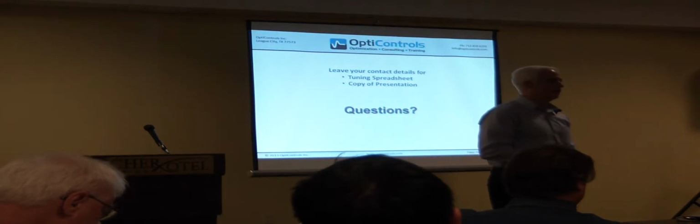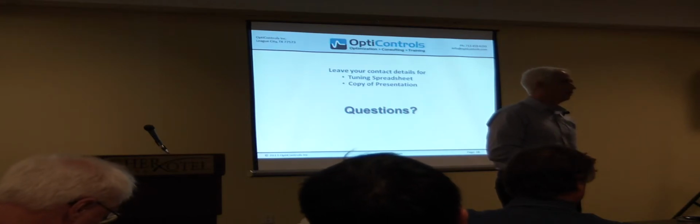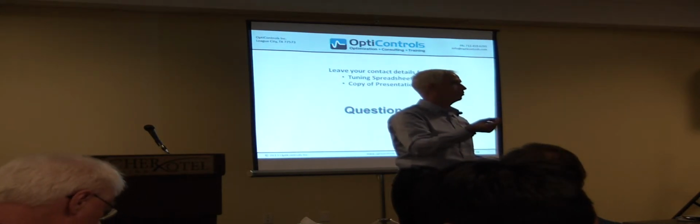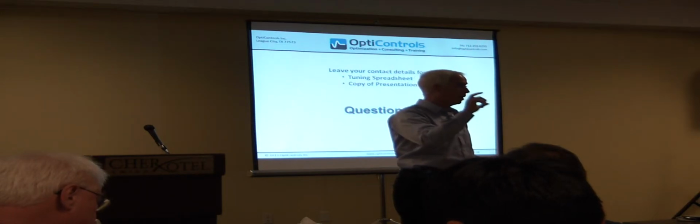No, I don't really have just a general recommendation. The positioners, they tend to be very fast. They act like integrating processes. If you understand the difference between integrating and self-regulating processes, a valve with positioner device acts like an integrating process. So you would normally use very little, if any, of the integral inside a positioner. And they would normally have quite a high gain. But what exactly that is, I can't tell you.